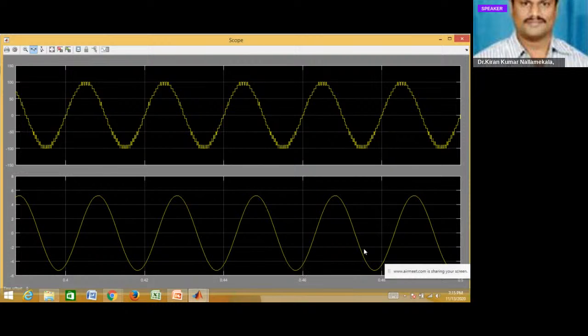Okay, so here it is a 21 level inverter and it is generating pure sinusoidal current. Even the dV by dt, if you see the dV by dt, it is very, very less. Okay, it is almost 10 volts. Whereas in the same inverter, two level inverter case, it is 200 volts. Here the dV is almost 10 volts. Okay, so this is the beauty of multi-level inverters.